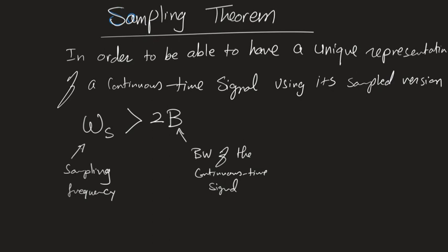And you know that your signal, that's what you found, is typically between 6, maximum 10 kilohertz. That's the bandwidth. So the minimum sampling frequency is going to be something like double that. If it's 10, then it's 20. And if it's 6 or 7, then the minimum sampling is like 12 or 14 kilohertz. They use a little bit more because that allows the quality of the sound to be more resilient to noise.